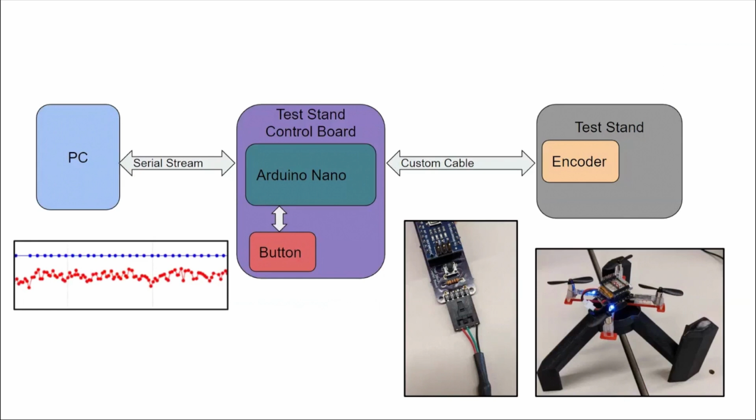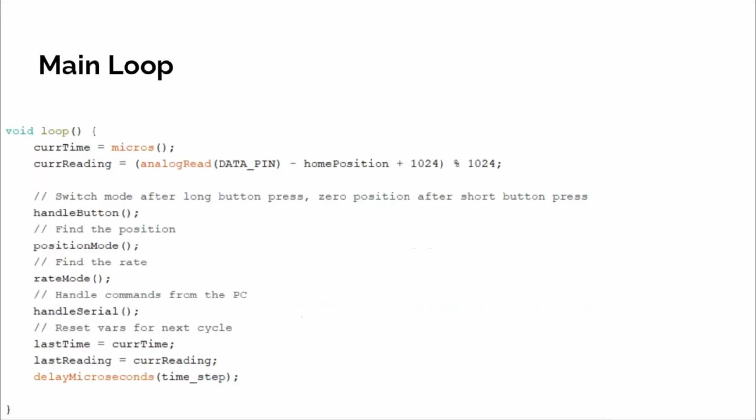This is offset to a middle value because we want the range of values to go from positive 180 degrees to negative 180 degrees. We then take some measurements for data for the different rate calculations. And then based on the mode, we either turn on or off the LED. Lastly, we start a moving average object called myRate. This averages out the last 10 values from the rate measurement, since the rate can often have a lot of noise. After the setup, we move into the main loop.